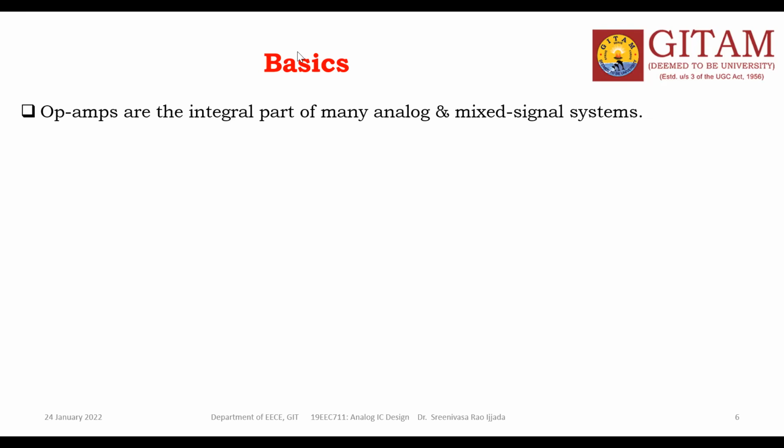As I told you, the basic op amp characteristics are very tempting for many applications because we have large gain, wide bandwidth, zero drift, higher input impedance, and low output impedance. These are the primary requirements for any amplifier.